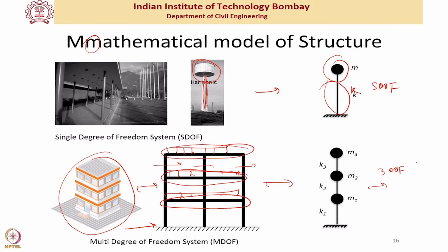Now you would ask which is the appropriate representation. Well, it depends on your problem and what you are trying to achieve through that problem. For some systems, even this could be represented by a single degree of freedom system, if let us say your goal is to find out the total base shear and not what is happening in the structure above. Or if your goal is to find out the story shears, then you need to represent it through a shear type building like this. So it depends on what you are trying to find through that problem.